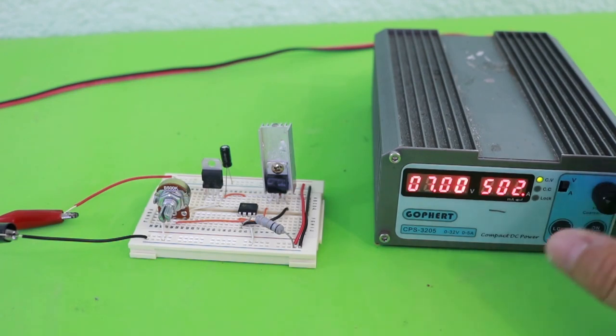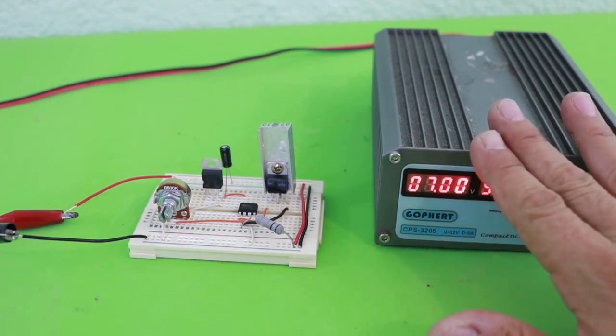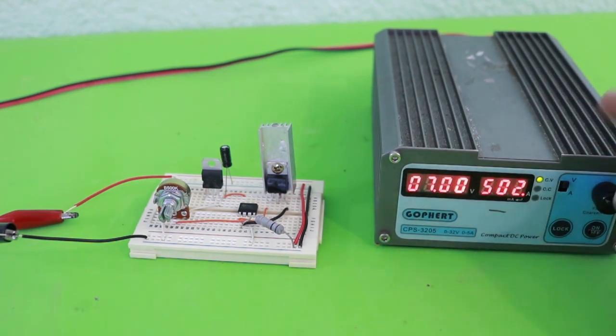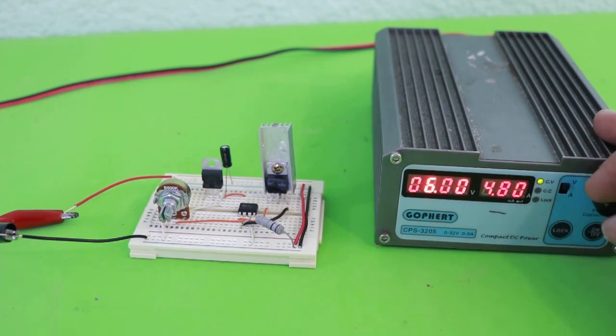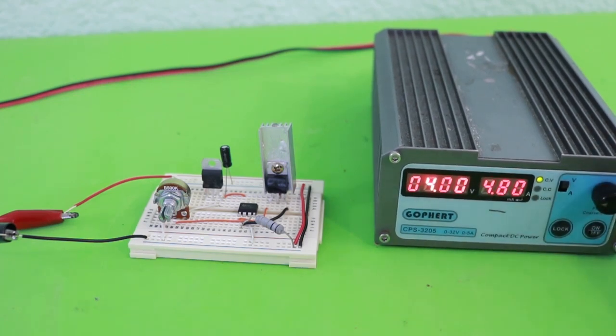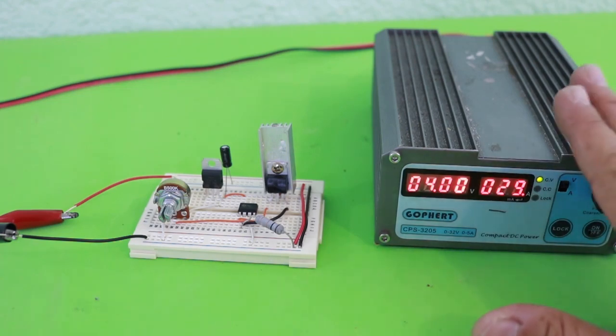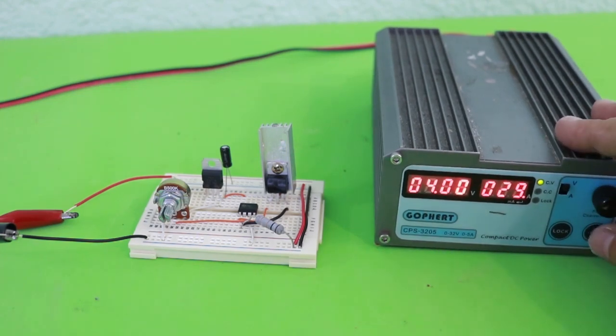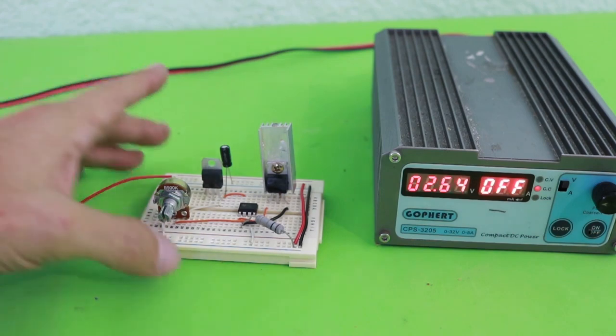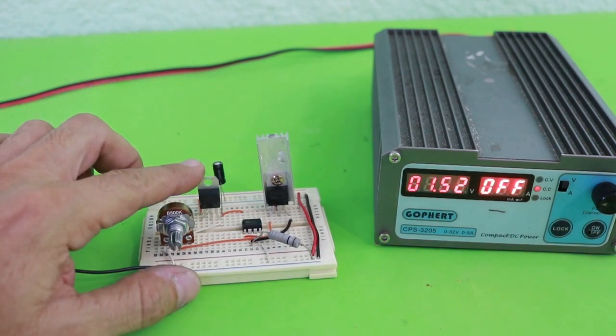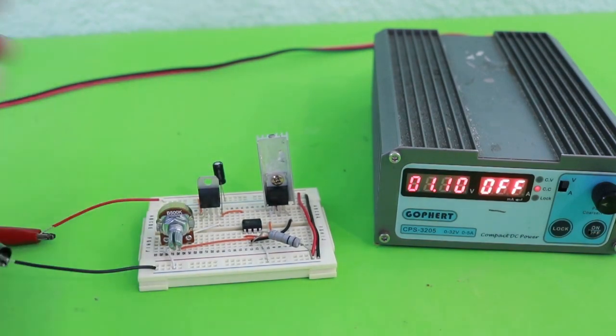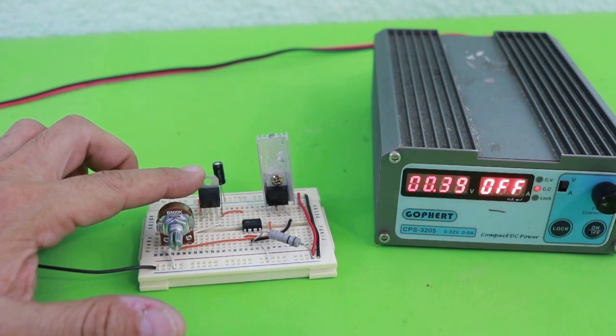There is a limit, however, to the minimum voltage that we can use, which is 5 volts. If we apply less than 5 volts, then the current no longer can be maintained, and the reason is that we need at least 5 volts to feed the voltage regulator. If we need to use less than 5 volts, then we need a separate power supply for the regulator.